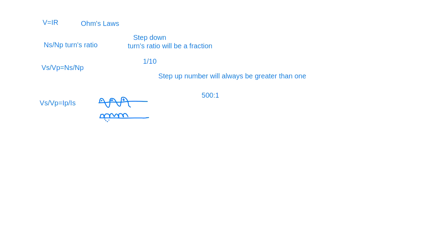So when I say I have 100% voltage ripple, that's what I mean, is that I'm always starting back off from that 0 and going to that peak and coming back down to 0. So it affects the efficiency or the energy of the X-ray.